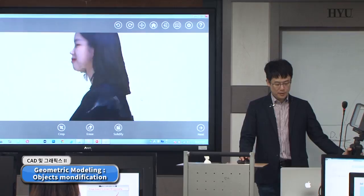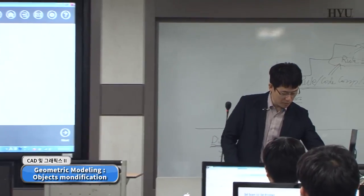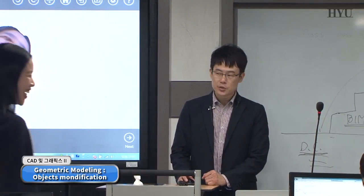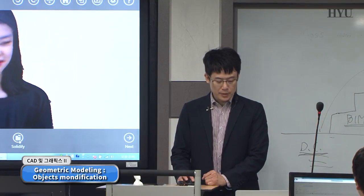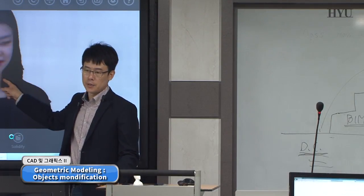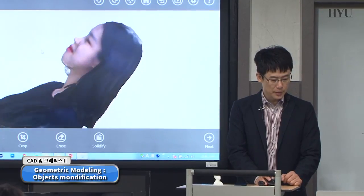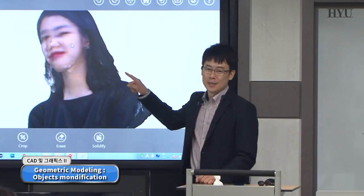Okay. Now we can see the 3D geometry. Of course, there is some problem. Even if you have some holes and some blank sides, and the chin part is blank, that's okay. Let me click solidify, okay? If you click solidify, this blank surface is going to be filled with some appropriate geometry. So now this one has solidified geometry, okay?